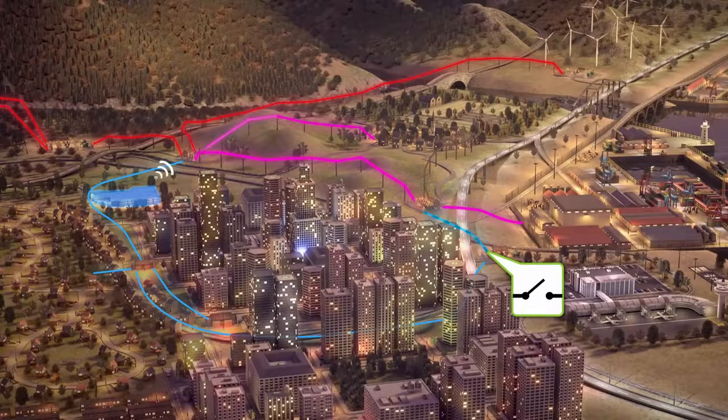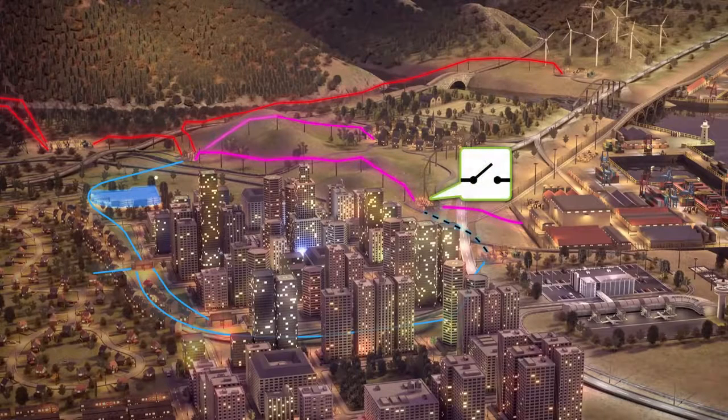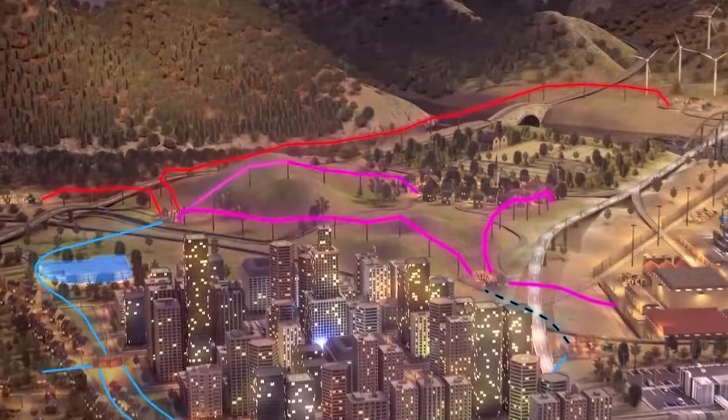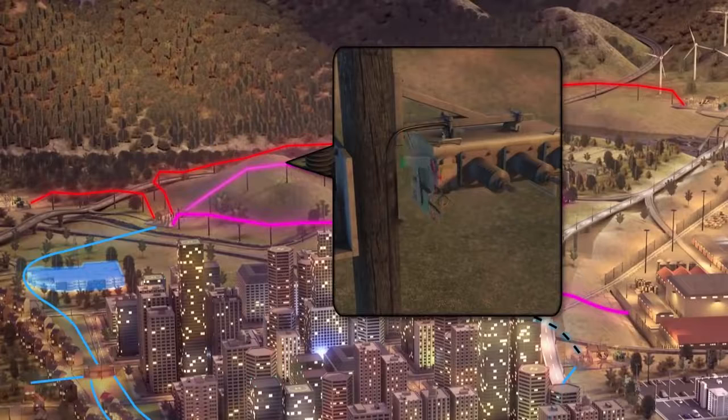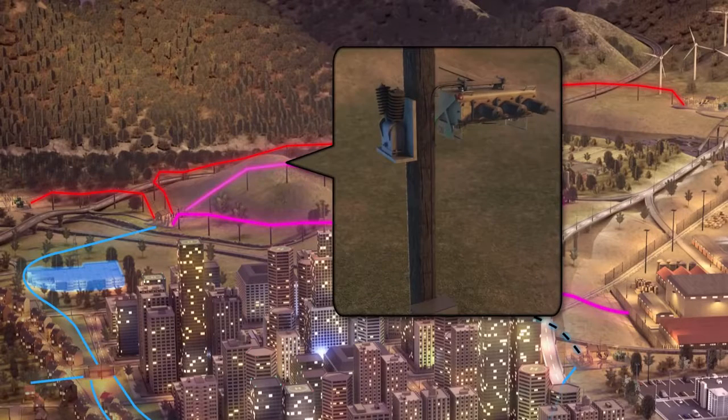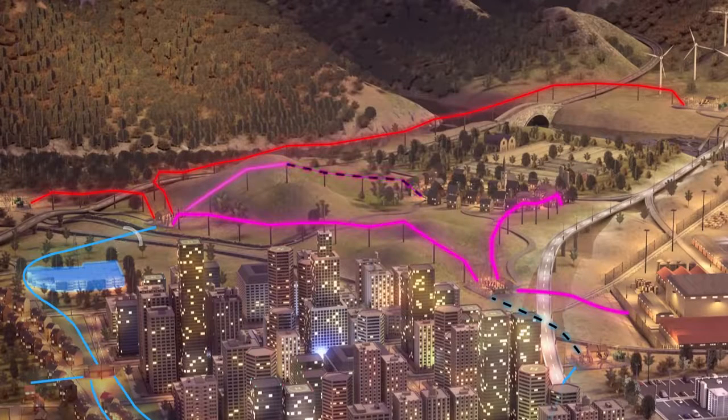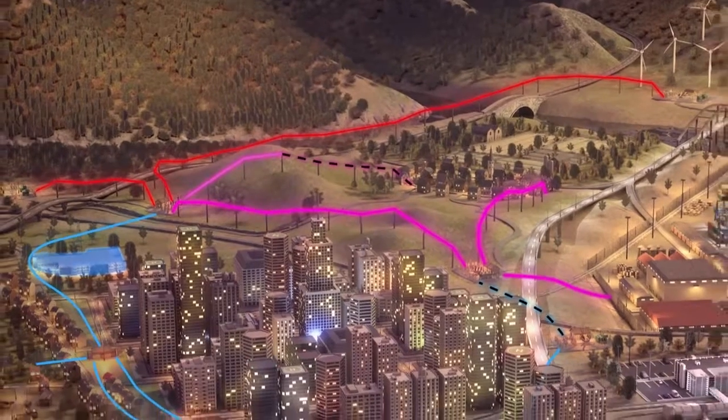With the load removed from the lower side of the network, the rural community outgoing switch from substation 2 is closed, creating a parallel circuit for the area. The final step for the SCADA operator is to reopen the GX switch to disable the backfeed to the rural community, restoring the standard operation of the whole network.